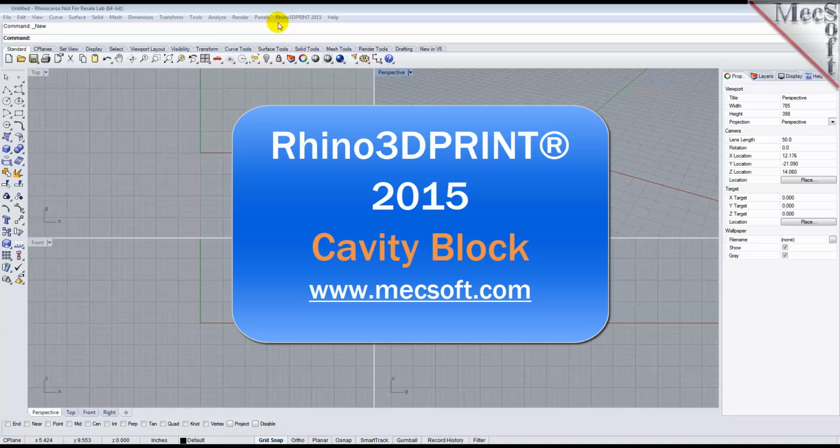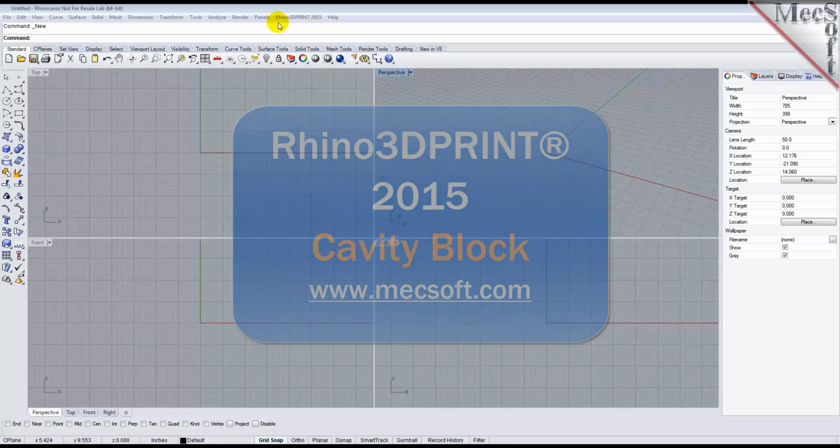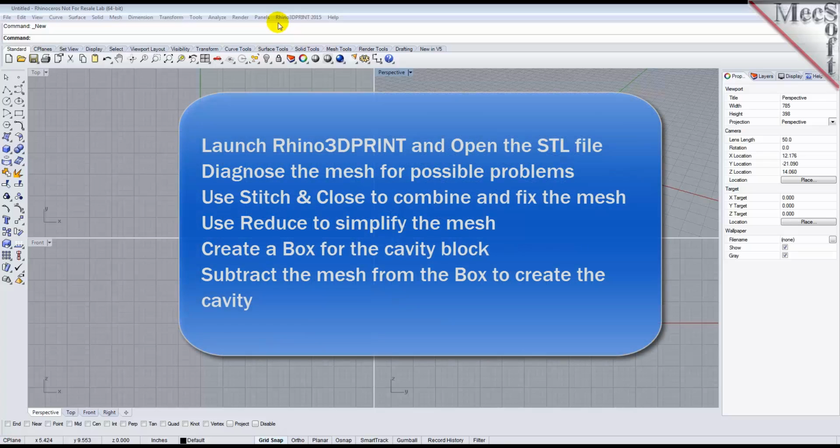Today we'll be working with an STL file to create a cavity block. We will perform the following basic steps to complete this tutorial. First, we will launch Rhino3DPRINT and then open the STL file. Then, we'll diagnose the mesh for possible problems. We'll use Stitch and Close to combine and fix the mesh. Then, we'll use the Reduce tool to simplify the mesh. After that, we'll create a box for the cavity block. Finally, we'll subtract the mesh from the box to create the cavity.